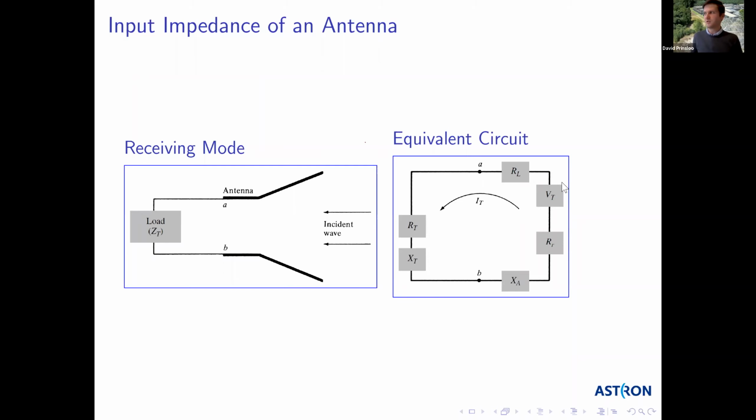So you've got your signal induced on the side of the antenna, and you've still got exactly the same impedance: the radiation resistance, the loss resistance, and the imaginary part of your antenna's impedance that you take into account. And of course, if you want maximum power transfer here, you want these two conjugately matched again, this time to your load impedance.